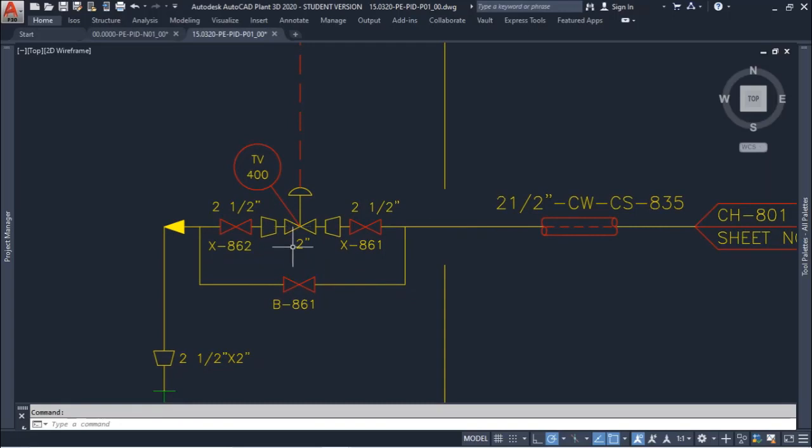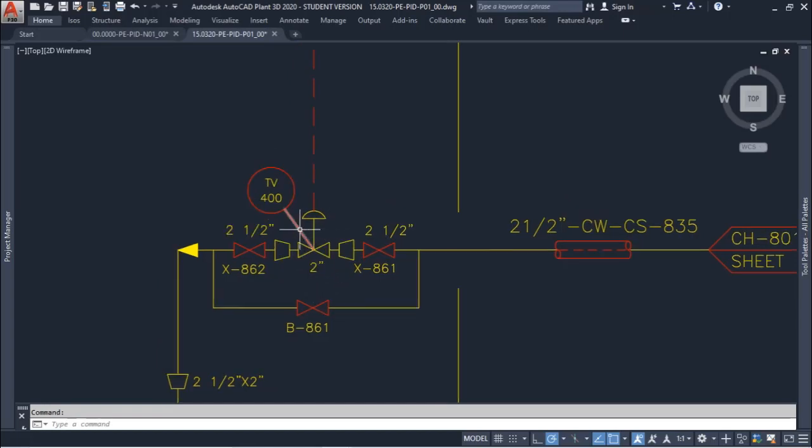But to confirm that, we need to go to the control valve specification data sheet, and we don't have the information about the signal range. But as it is a control valve, and this is the representation of a diaphragm, it needs instrument air, although it is not shown in the P&ID.